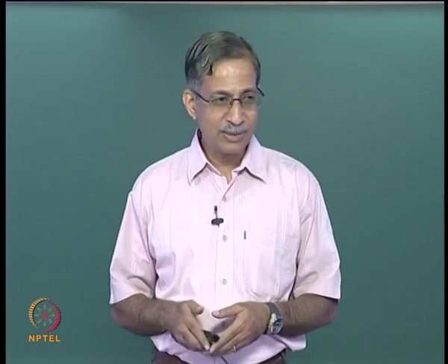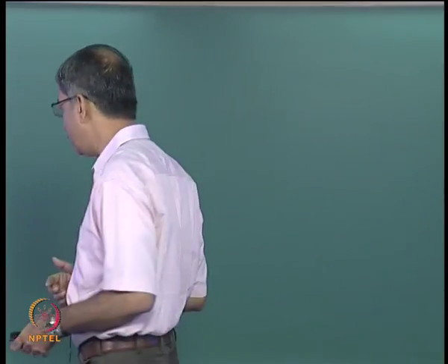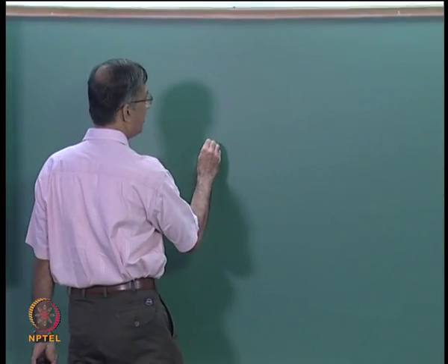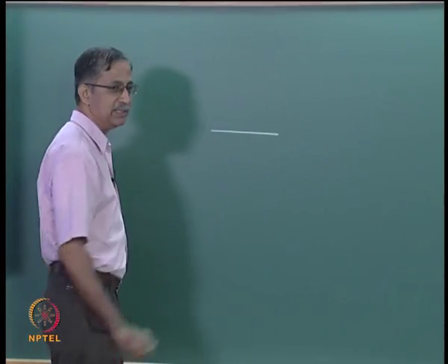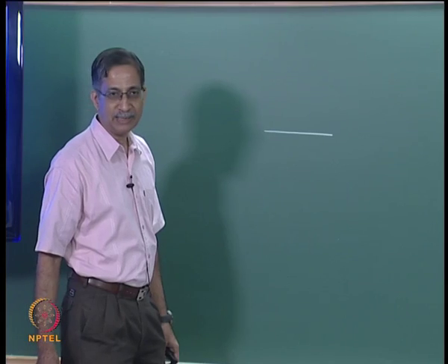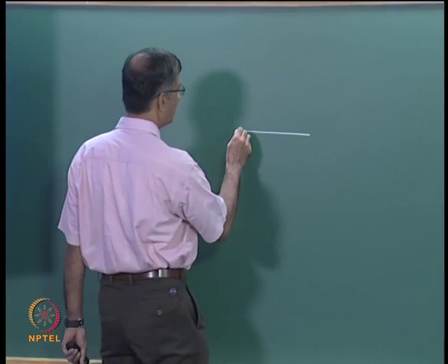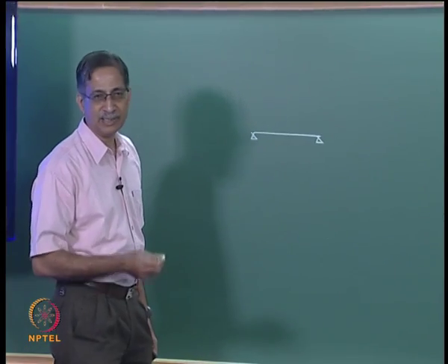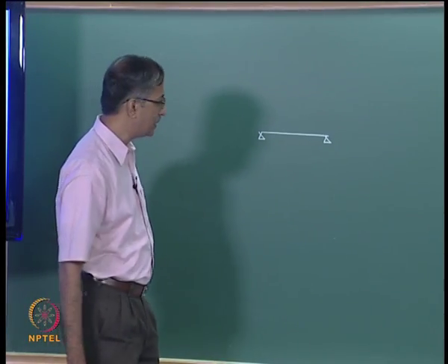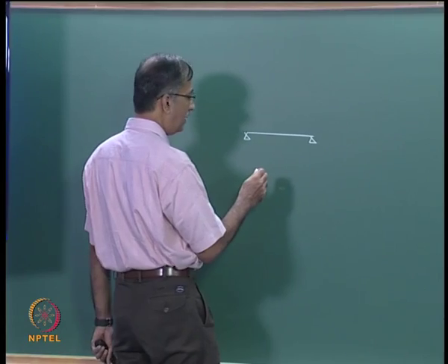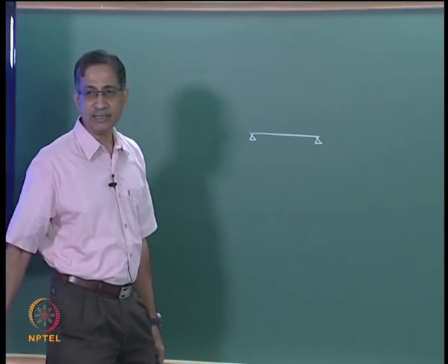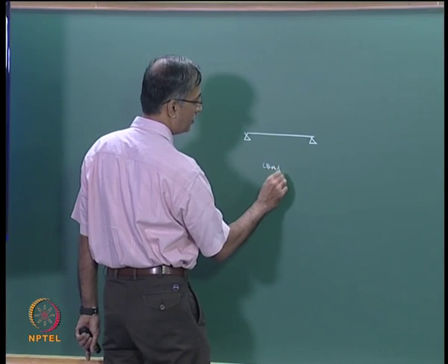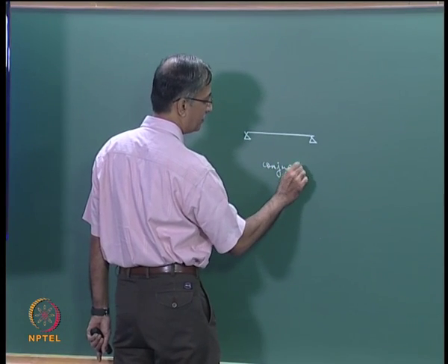How do you start from scratch? Always go back to the conjugate beam method. In the conjugate beam method, what are the boundary conditions for a simply supported case? It is simply supported. Whether you put a roller or not does not really matter because we are ignoring actual movements. So what is the loading diagram on the conjugate beam?